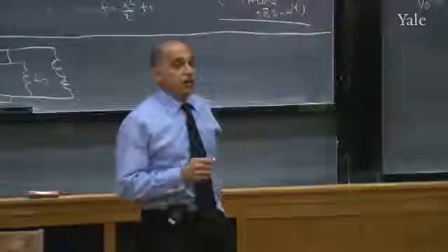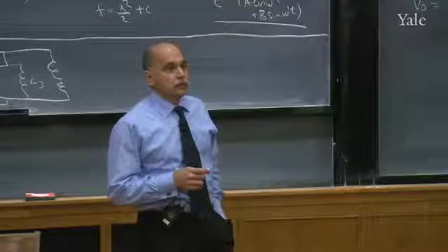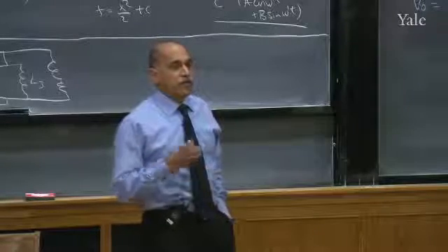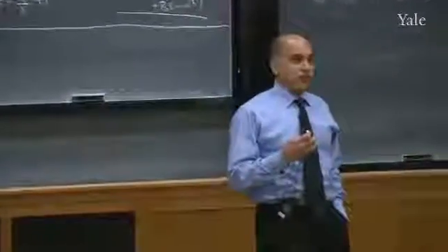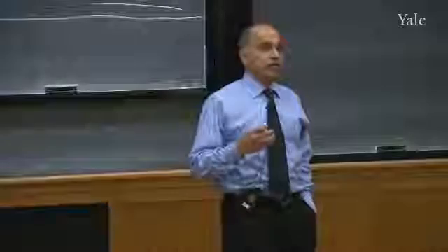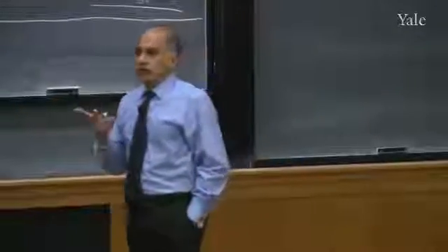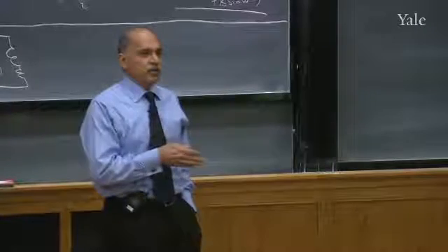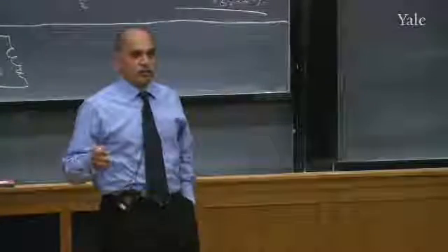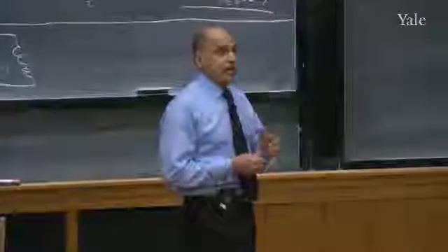So your procedure, yep? Is there any physical significance to the imaginary part of the solution? No. If you want, the imaginary part of the solution is the answer to a person whose voltage source was V naught sine omega t. Okay, so you are solving two problems, but we believe that it's nothing new. Because if you can do cos omega t, the answer to sine omega t is the same, except you shift by pi over 2. Everything looks the same. But it answers that question.